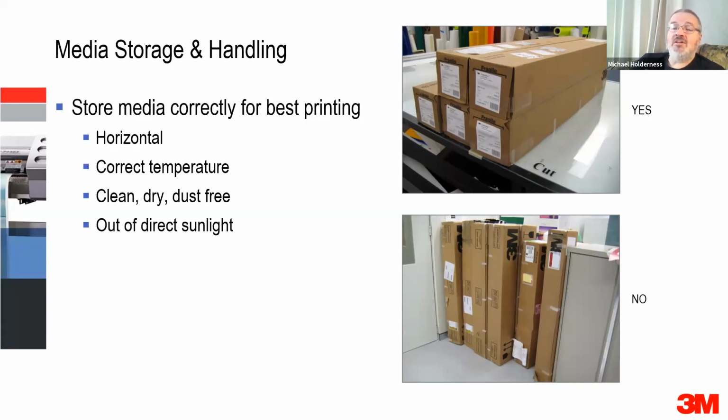But that's going to be very, very dependent on what you're printing. If I was printing a banner with great big thick layers of ink, then I probably would turn on both and turn them on full bore because you're going to need all that power to cure it. It really depends on how much ink you're laying down as well. Good question, thanks. Cool, thanks, Mike.